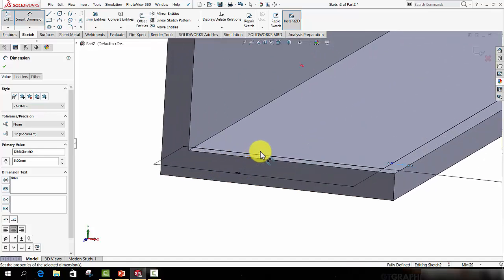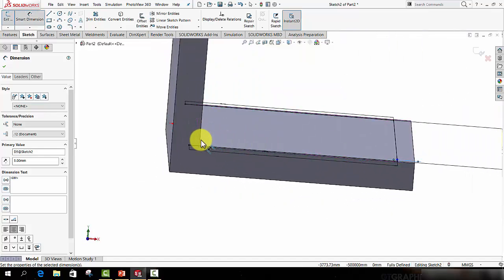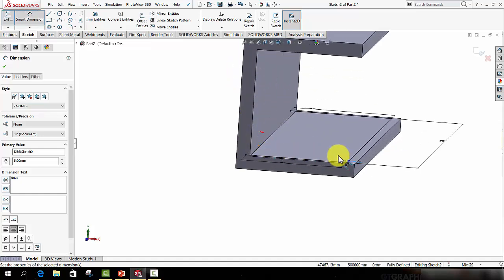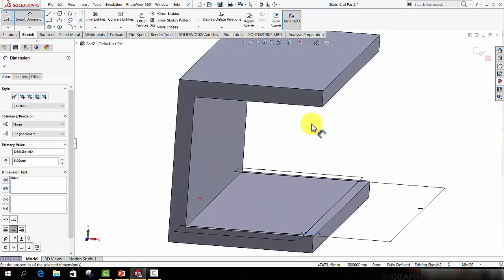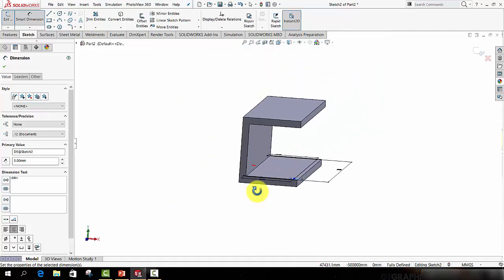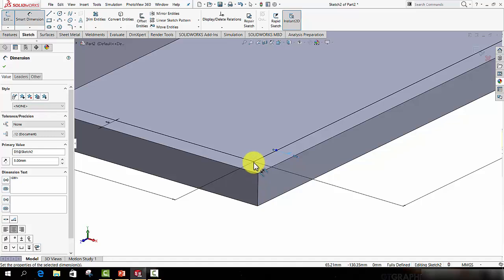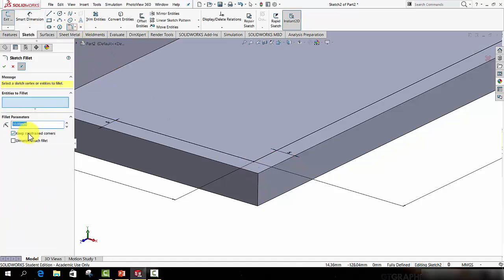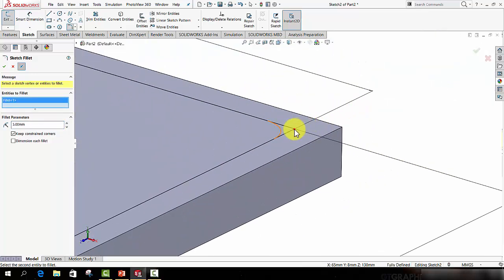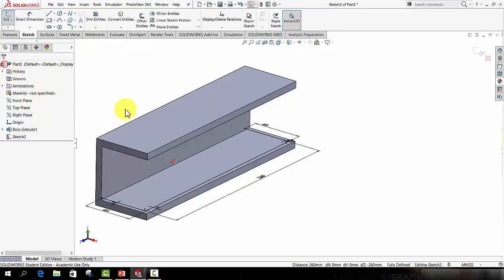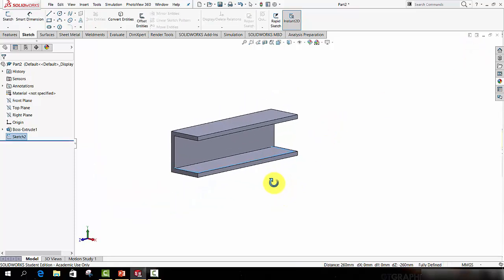So it's important to note that that black line that I've drawn actually goes into the back, this vertical portion of the plastic casing as well, and I want that. I want the mesh to bed 3 mil down into the base, 3 mil up into the top, and 3 mil back into the back. So I'll close that sketch. In fact, before I do so, I'll just put a fillet on the corners with a sketch fillet. Let's pick a radius of 5 mil, 5 mil, and 5 mil there. So press the green tick on the left to close the sketch fillet, and the green tick up here, or the close sketch up here to close the sketch.